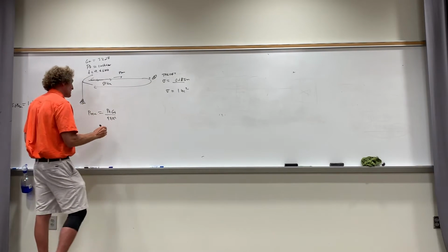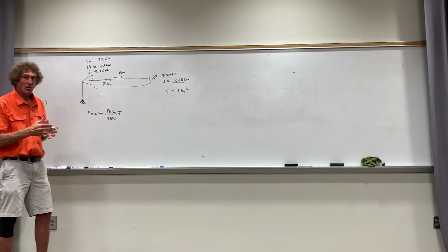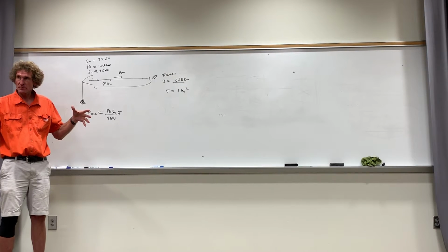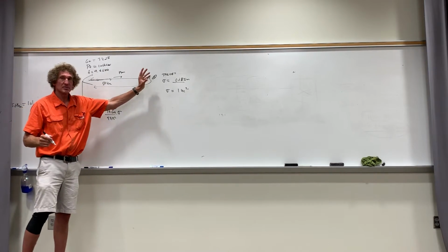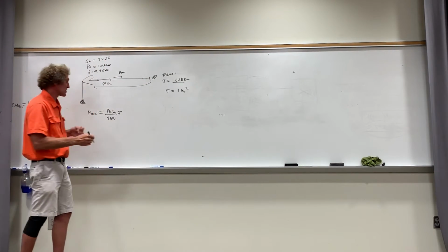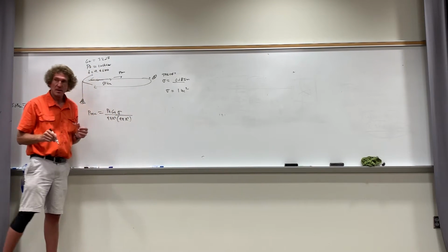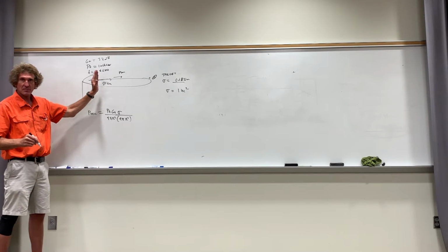So now we multiply this by sigma. Now we have all that, this much power is going to be scattered. And the scattered power, doesn't it fall off as 1 over r squared? Right? You come down with a pulse, bam, it starts falling off, and we assume it's isotropic. So then we divide that by 4 pi r squared again. Now that's the power density coming back, the reflected power density, right?